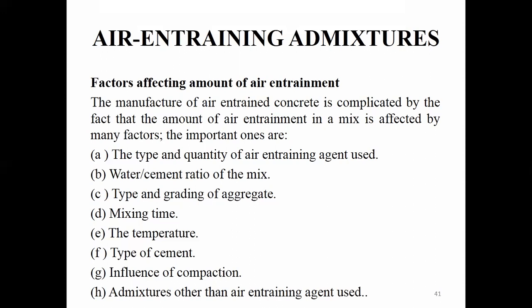Can you understand? So you are making concrete, right? You will be adding all the ingredients together and mixing them together. While mixing, in addition to the concrete making materials, you will be adding some amount of air entraining admixtures. This causes some air entrainment in the concrete, we all know very well. So what happens when you keep on mixing that mix over some time? The air bubbles present in the concrete will get reduced. So the mixing time is also influencing the amount of air entrainment in the concrete.